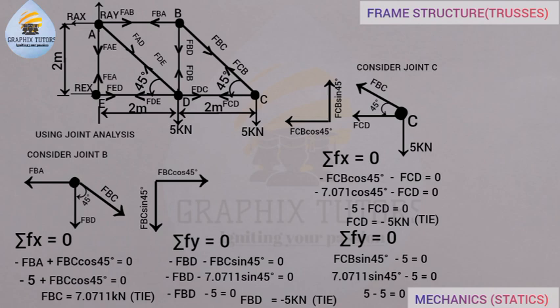So you can actually check if you go to point D. Let's just check if we're actually on track. Because when you continue, if you have 5 joints, you're allowed to calculate for just 4 joints. And if you check your joints very well here, we have 5 joints, which are joints A, B, C, D, and E. So you're only allowed to calculate for 4 joints. I calculated for E, A, B, C, so I will just leave joint D. If I use C, E, A, D, I'll leave B alone. If it's 6 joints, you're allowed to calculate for 5 joints. If it's 7 joints, you're allowed to calculate for 6 joints, right? So that's what we are doing here.